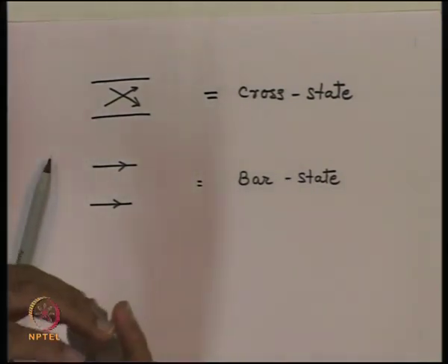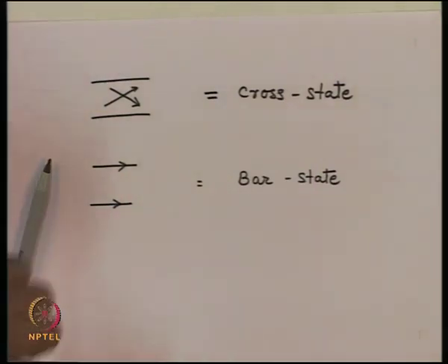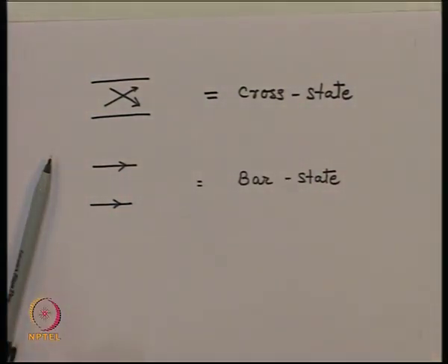So, if we take the directional coupler and make this on an integrated optical device, then by applying the control signal, either I can put the connection into cross mode, or by not applying the signal, you can put the signal into the bar mode. Once you have this basic configuration, then we can build a complex switching network around it.